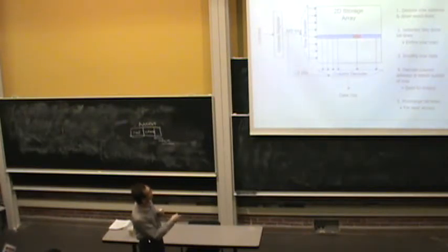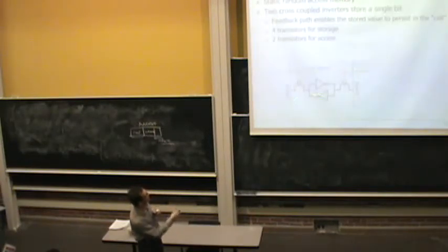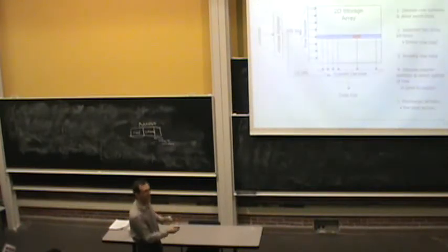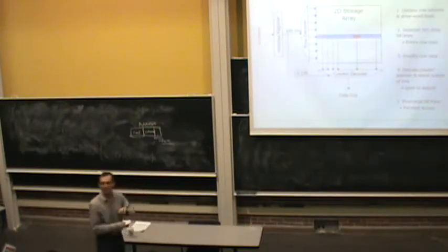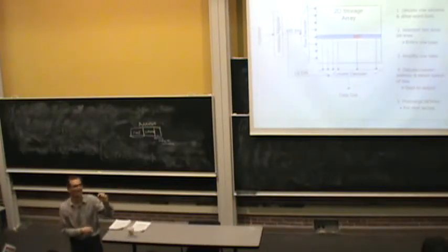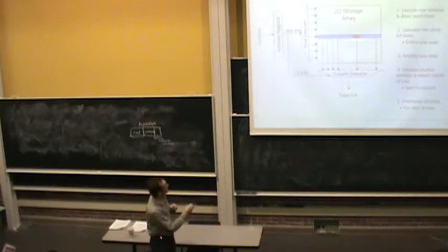And at the end, there's an operation called pre-charge. You pre-charge the bit lines because once you read, you disturb these bit lines. Now, bit lines are charged with whatever you read, so you pre-charge the bit lines to their original state, so that the data you read next time will not be affected. You've seen all of this before, right? Yes? Okay. So this is independent of the technology.